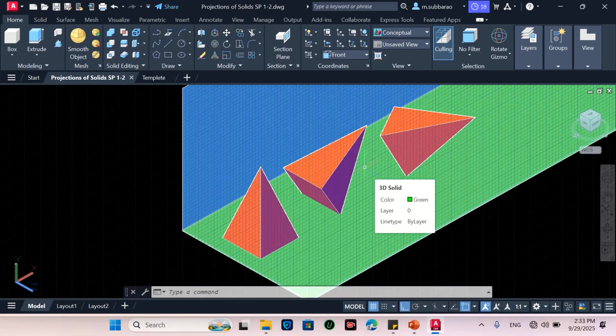So now let me demonstrate the views of this solid in these three stages. Now this is the first stage where I am imagining, this is actually the final stage of the solid, but in this final stage I can't directly draw the front view and top view of this solid. So I rotate, and I will imagine that the axis is making 60 degrees with the vertical plane, but I will make it parallel to the vertical plane. So then I will get the position of this solid.